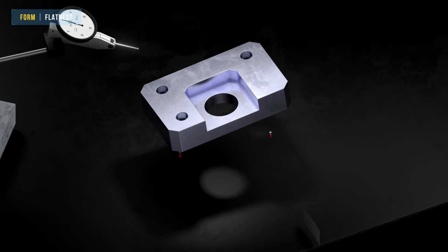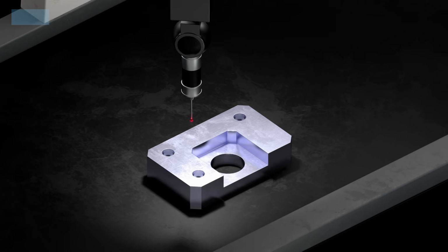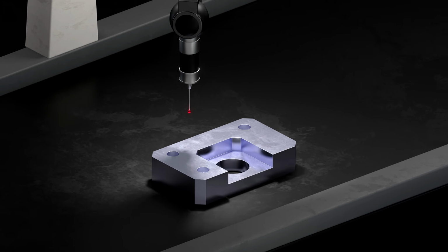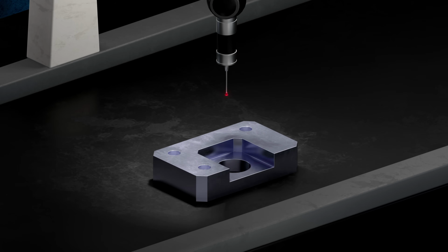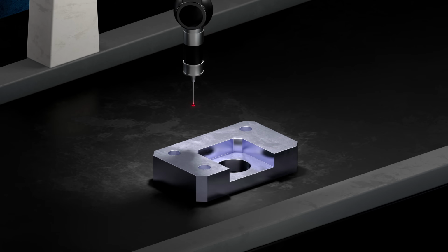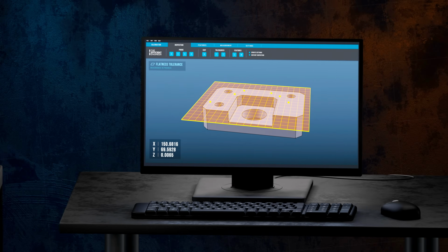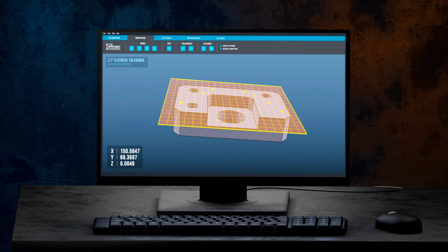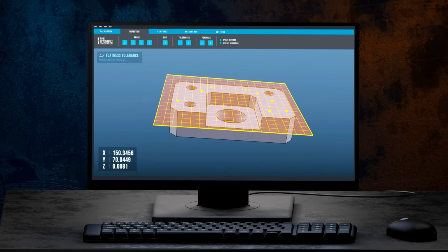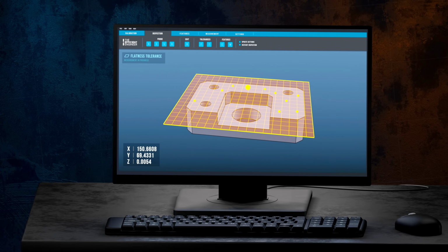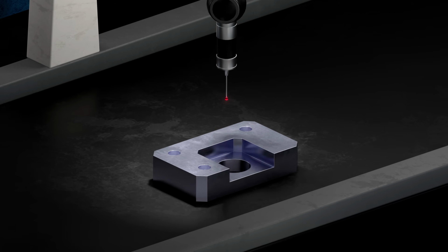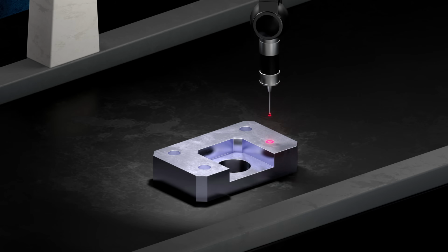Another very common inspection approach is to use a CMM, a coordinate measuring machine. A computerized probe is used to take measurements that are fed into software that then uses algorithms and curve fitting to determine deviations from the perfect size. CMMs are expensive pieces of equipment, but can be used to inspect any kind of geometric tolerance.